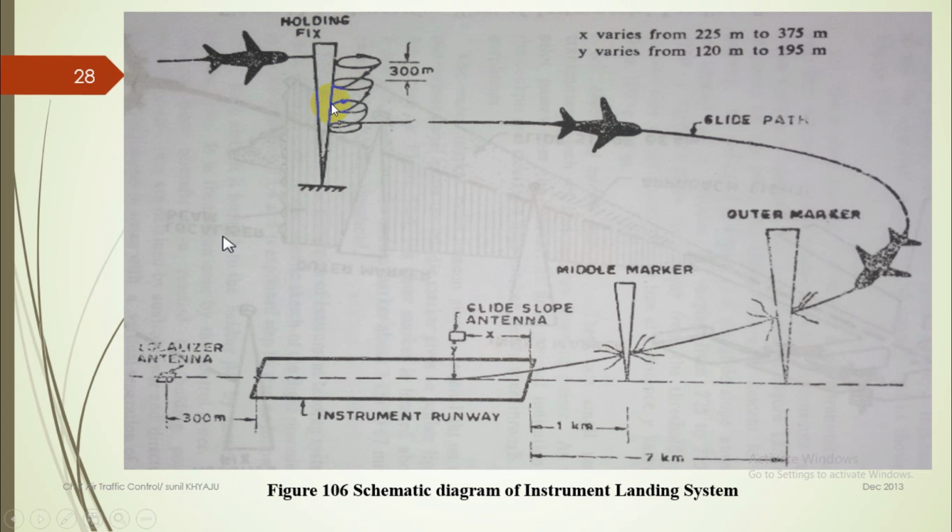If two or more aircraft have reached the holding point simultaneously, they are detained by the control tower and directed to keep moving around in space with a vertical separation of at least 300 meters. After every 2 minutes, the airport control tower directs the aircraft at the bottom of the stack to move out for the final approach to the runway.